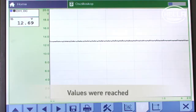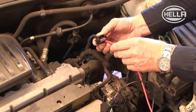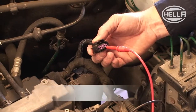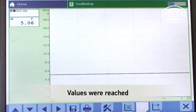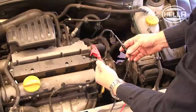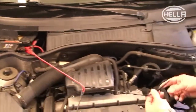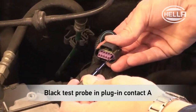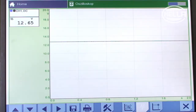Switch on the ignition and read off the measured value in the diagnostic tool. In this case, the voltage supplied to the solenoid coil reached the specified values. Next, check the voltage supplied to the position sensor by inserting the red test probe into plug-in contact D. After switching on the ignition, it becomes visible that the supplied voltage is within the specified range here as well. To check the ground connection of the EGR valve, connect the red test probe to the positive battery and the black test probe to plug-in contact A in the connector housing. This also reveals no fault.